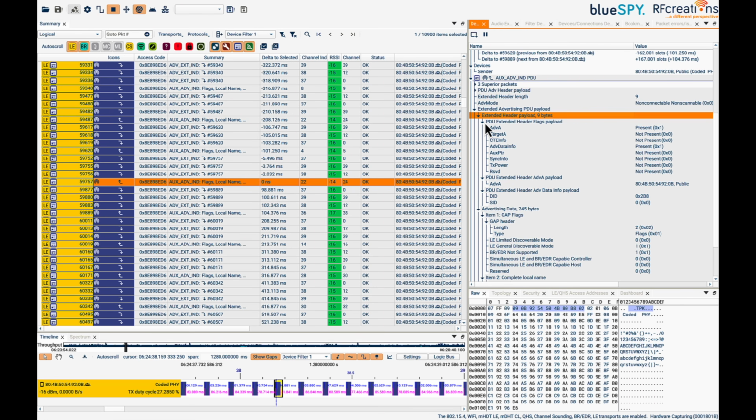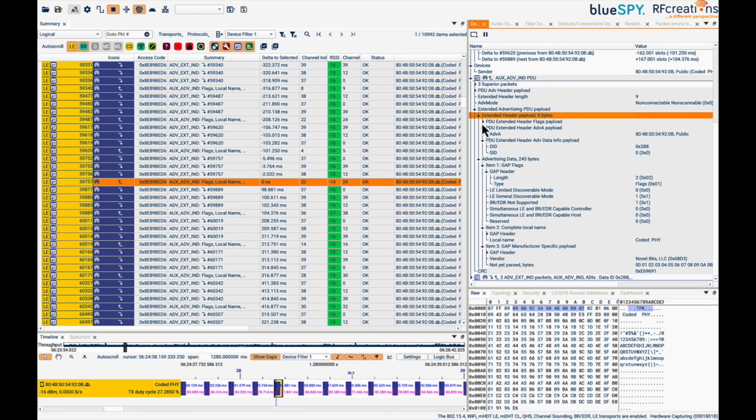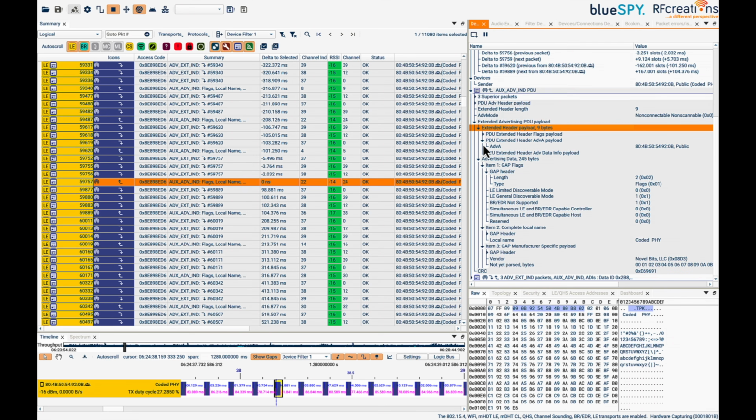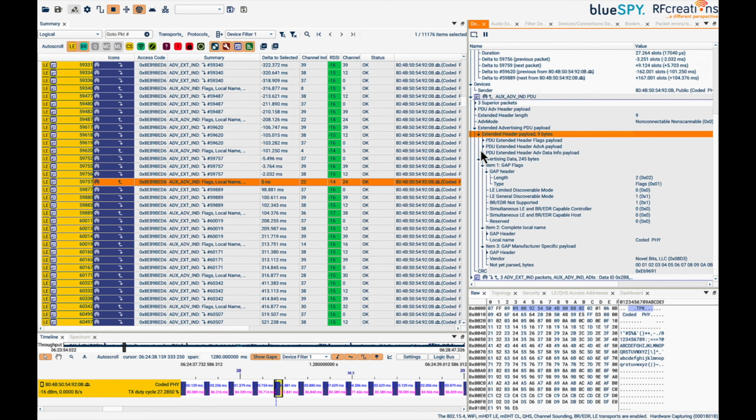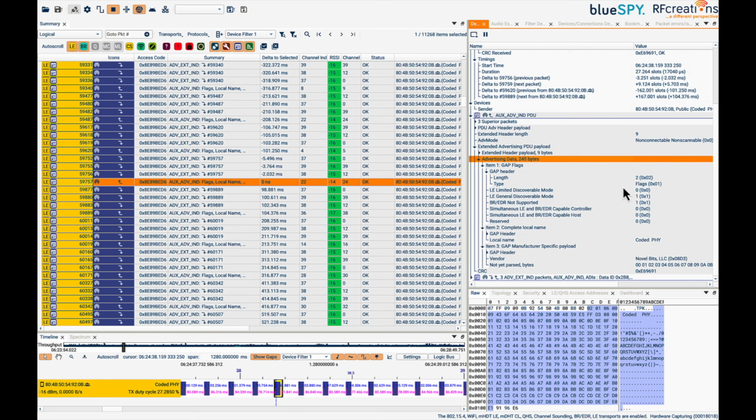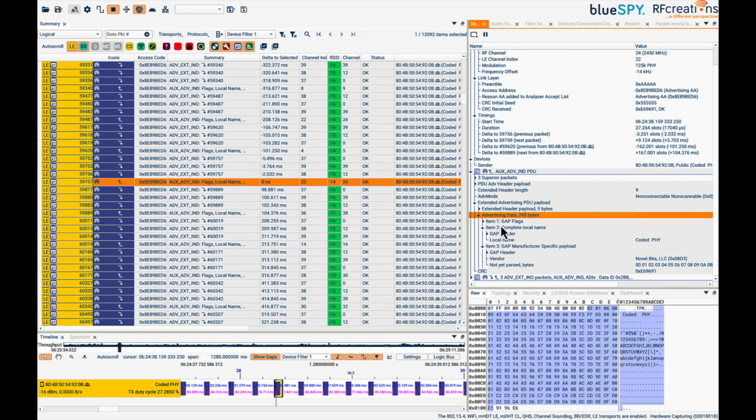But here we can see what's included. I won't go through all of that. I will skip and look at the actual data. So we're going to look at the advertising data. It looks like it's 245 bytes. If you add that to 9 bytes, you have 254, which is the maximum that we talked about. And then we have the length plus the advertising mode all equal 1 byte, and so together it'll be 255 bytes. So the first thing we have is the flags, and it's 020106.